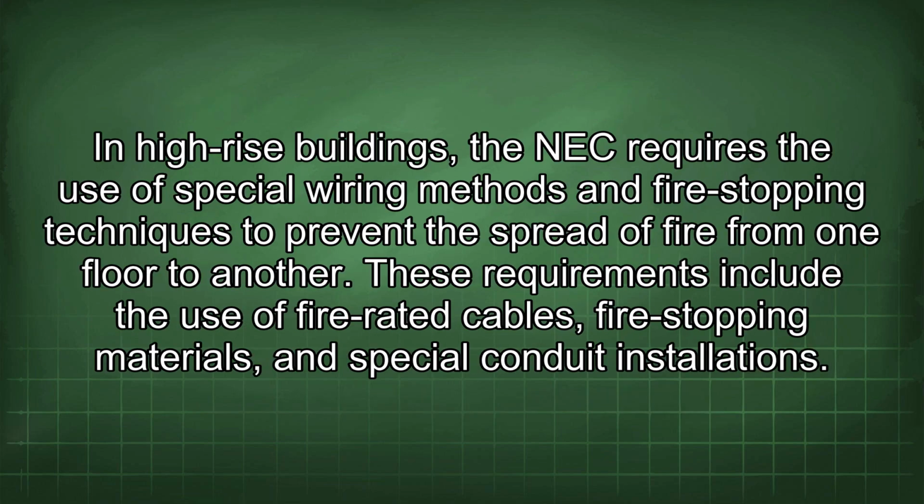In high-rise buildings, the NEC requires the use of special wiring methods and fire-stopping techniques to prevent the spread of fire from one floor to another. These requirements include the use of fire-rated cables, fire-stopping materials, and special conduit installations.